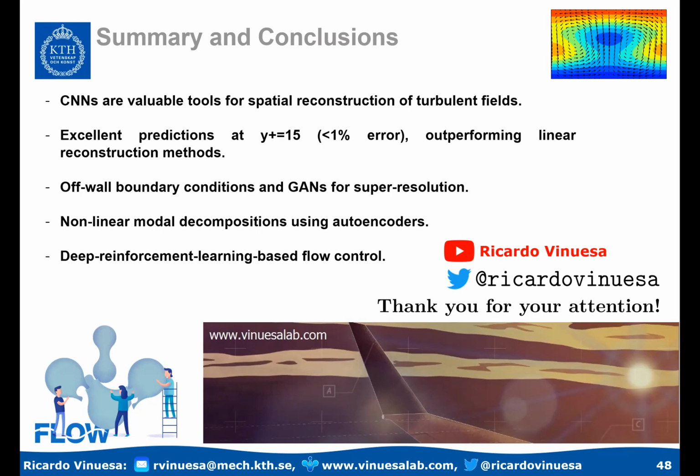Using only the pressure field, the results are worse, obviously, but of the same order of magnitude. So it doesn't change very much. If you want to predict very well the u prime, then the streamwise wall shear stress is the best variable. It's most highly correlated. But if you want to predict everything, just using the pressure is still quite good.